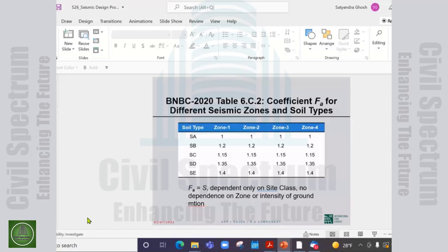If you want to look at all the historic earthquakes and exclude the entire range where the past earthquakes have been strong, then you won't have much to work with. So my advice would be don't worry about it. Design your building properly according to code, and then if there is resonance, that is fine. The building will still do okay.